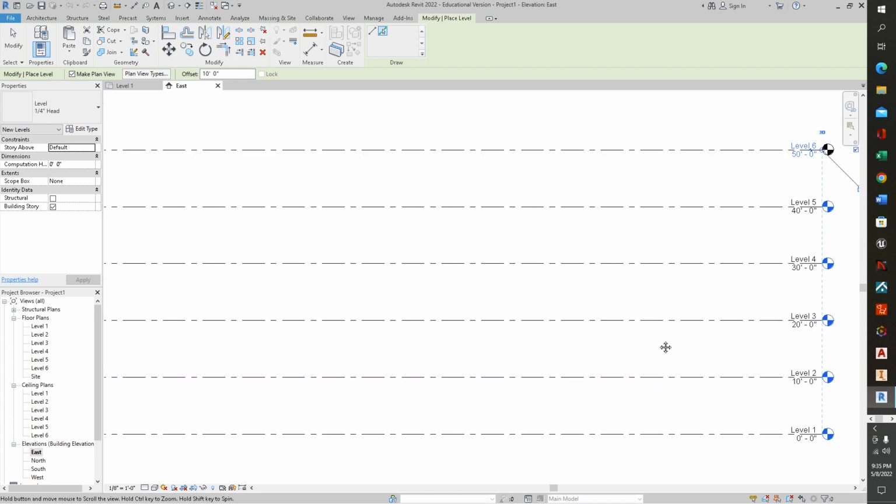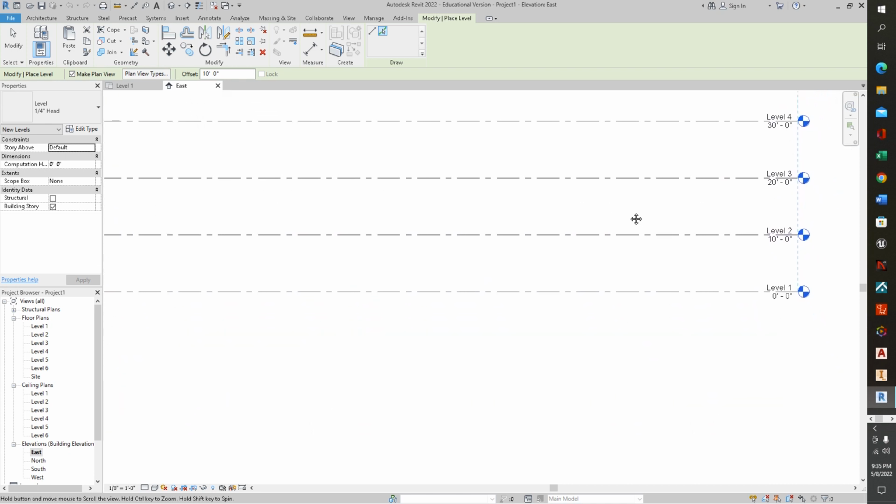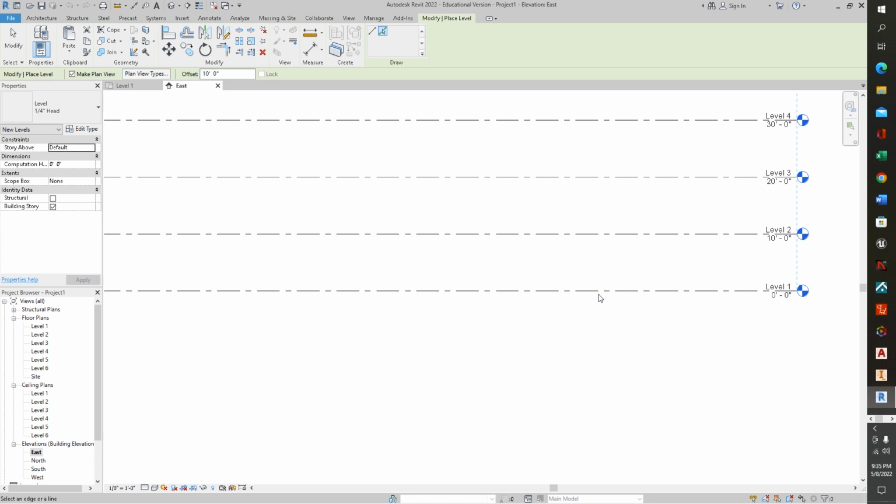We're just doing a quick example. 6 levels up, and we'd like to maybe put 1 down. So we'll go 1 level down. That adds us a 7 at the bottom here. But before we do anything to change this to not being 7, because of course floor 7 would be a rather confusing thing to find below floor 1, we would like to change that to basement or foundation. We'll change it to foundation in this case.